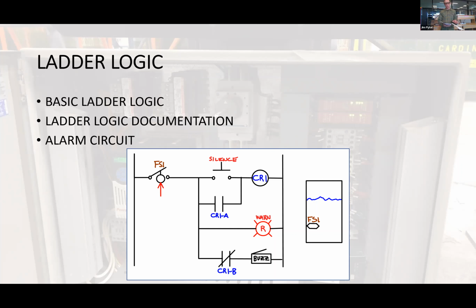So that's our first lab where students actually wire something up. It's a great experience for the students to get some hands-on experience with it. Another important thing that the students learn in this early lab is wire numbering. Any of you who have worked in something really large and industrial, for example a wind turbine, know there are hundreds and hundreds of wires there. If they're all the same color, it'd be impossible to find anything. Getting used to wire numbering and working with a partner is important too. Under COVID, I've been working as a single person, but I previously had students work in pairs, which I actually like a lot better. They're capable of checking each other's work.